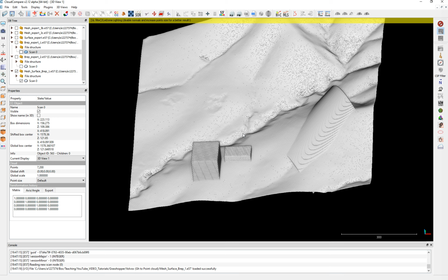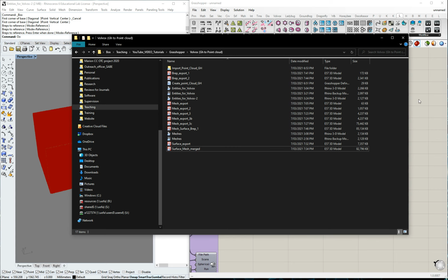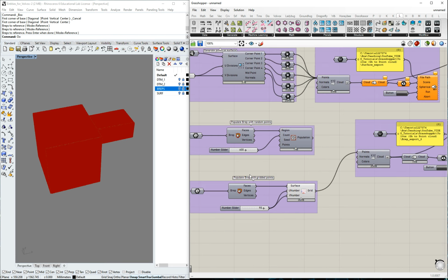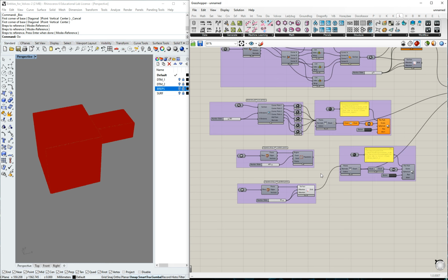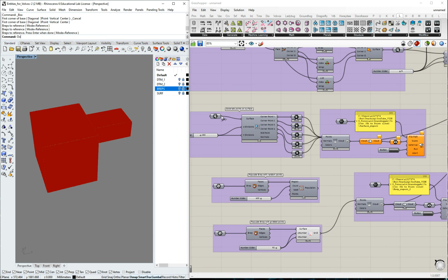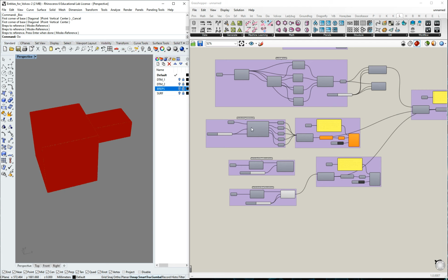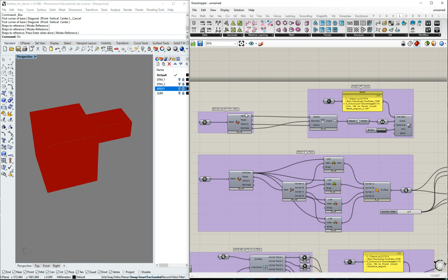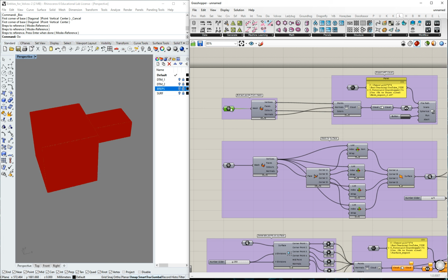Now, the most important thing here is that whatever you're doing, you try to find the best method for populating the surfaces and converting, either using a mesh or a surface. Now, breps are pretty straightforward, and they usually help for representing volumes. If you have complex organic shapes that are meshes, there you want to export the mesh directly, like this one. Don't forget to flatten. Or you may want to, in this case, export directly. But this mesh, it will depend on the number of points.